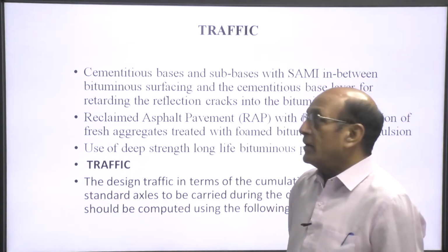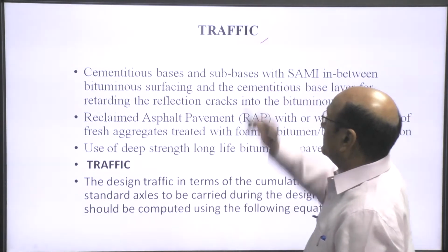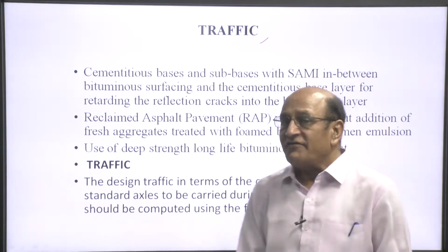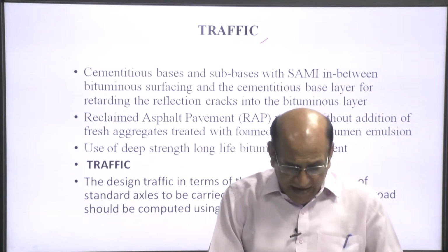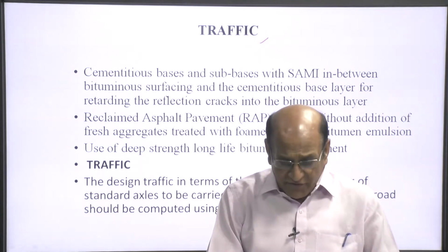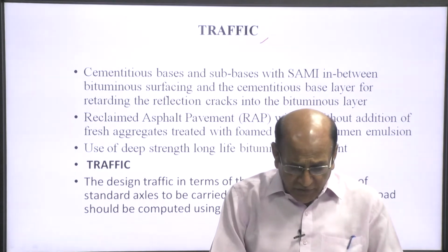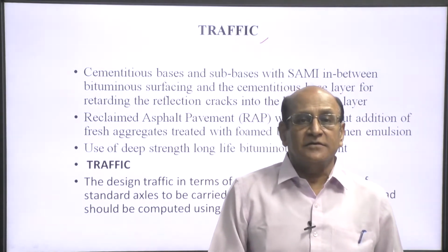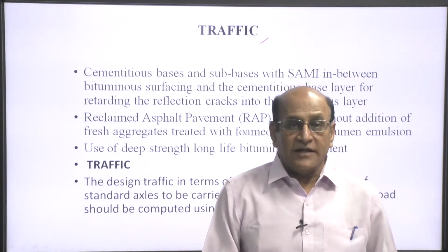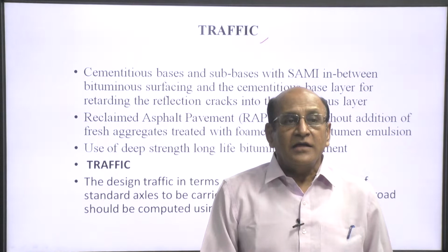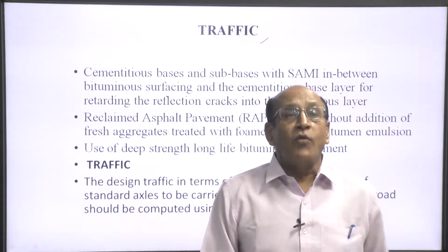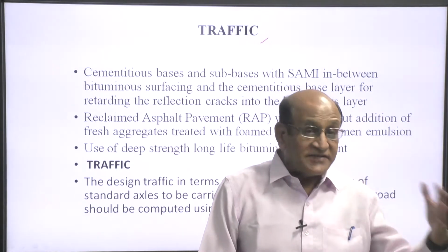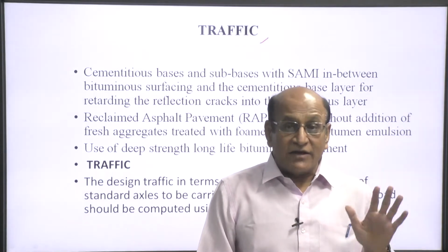Now, come to the first parameter, that is traffic. The design traffic in terms of cumulative number of standard axles to be carried during the design life of the road should be computed using the following equation. We have discussed in the previous lecture that if a vehicle is going on a highway, even with more load, there will not be any problem. But when there is a repetition of load, then there will be fatigue failures.